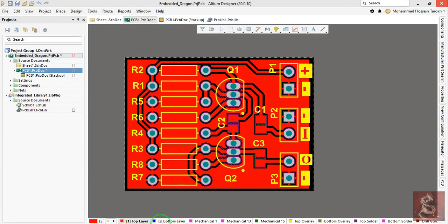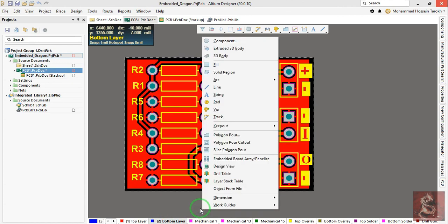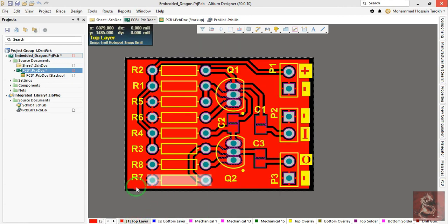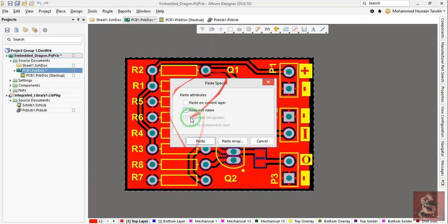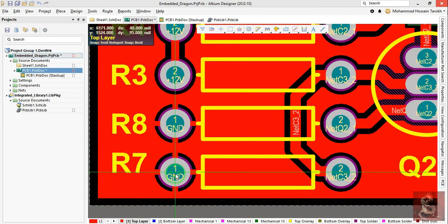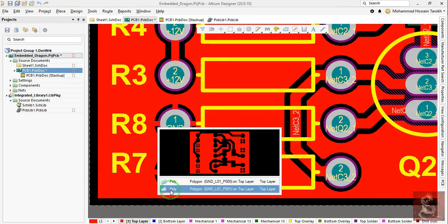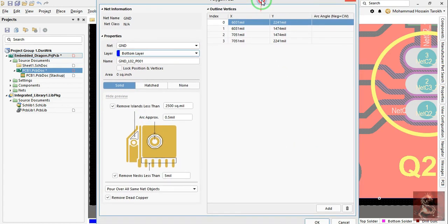So we have two layers, and as you see, in our case, it depends on the frequency of operation, but for such a device it's not a problem and it works fine. But it's always good that we have the polygon layer also here. So for this case, we can copy the ground on top, all the plane, and by pressing EA and keep net name, paste, then we have it here. So we have two of them now, and we change the name of the layer, and it's done.